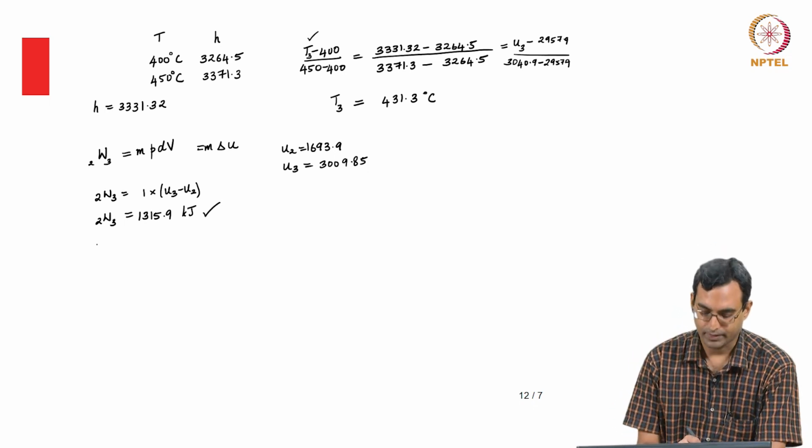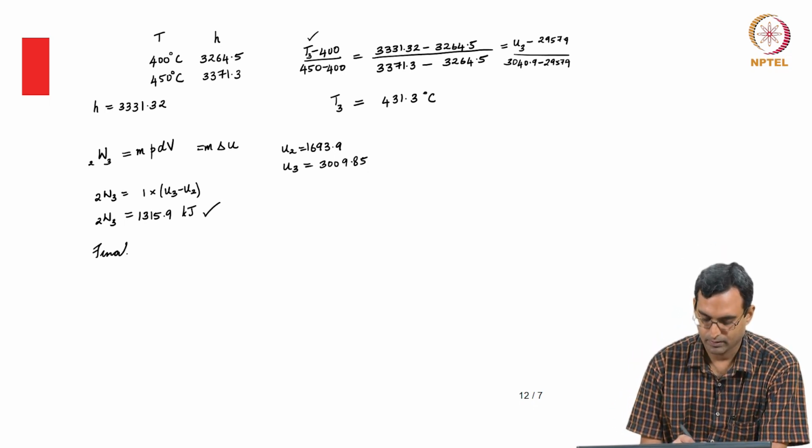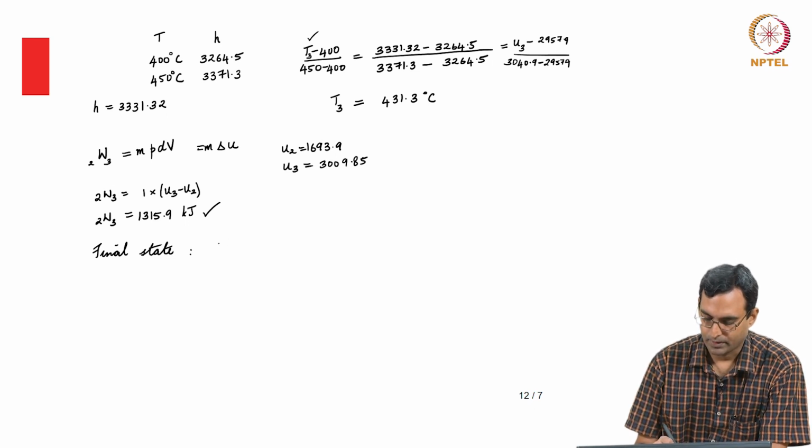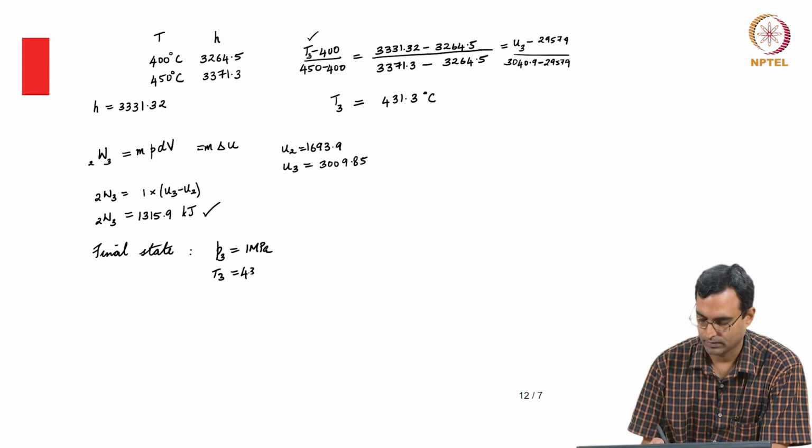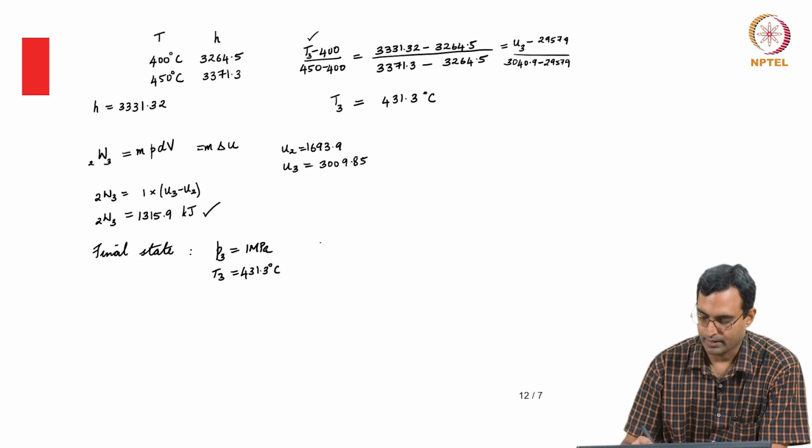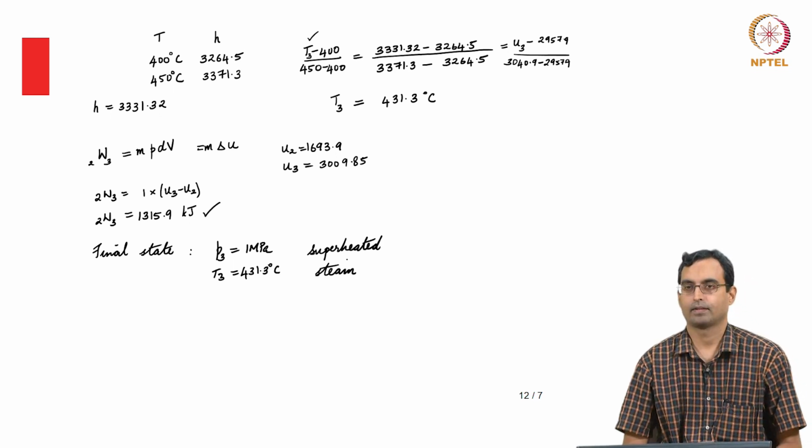So, in this way I have both the work done in this process as well as the final state. So, the final state is a pressure of 1 megapascal, a temperature of this, and it is superheated steam. That is essentially what I see.